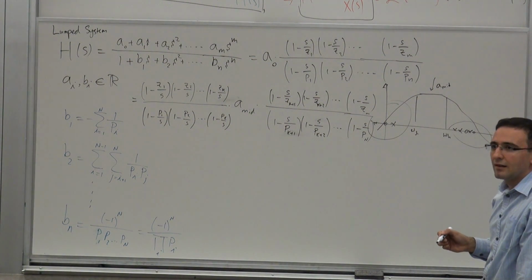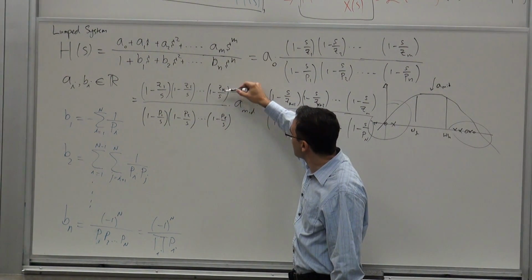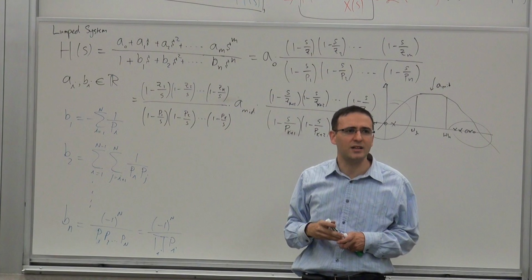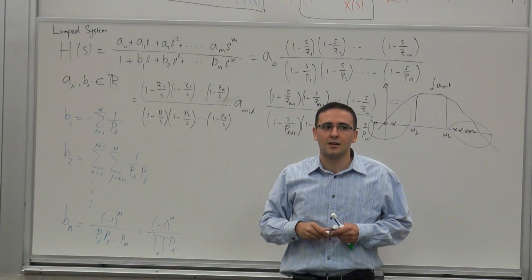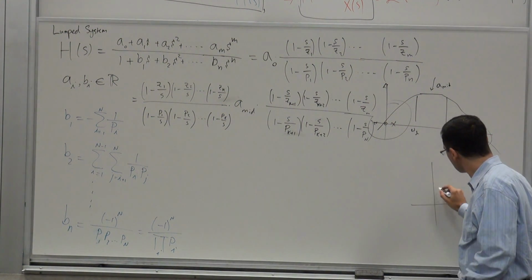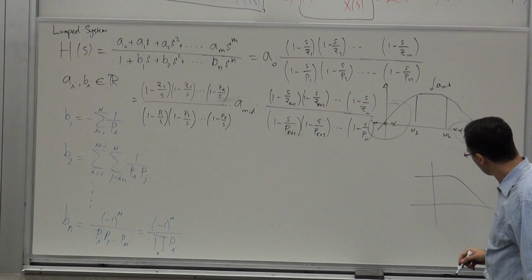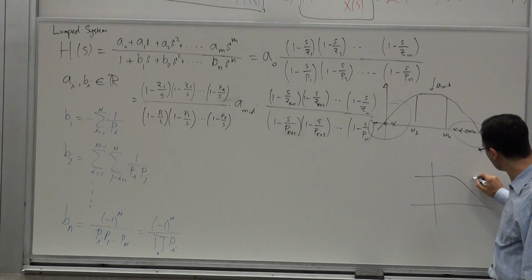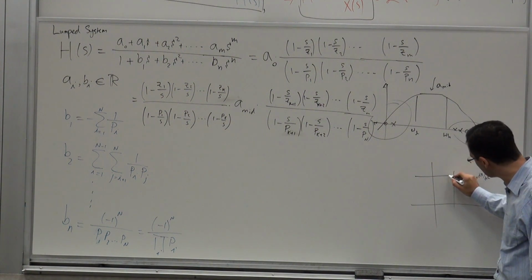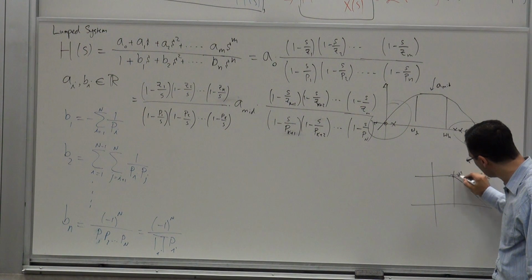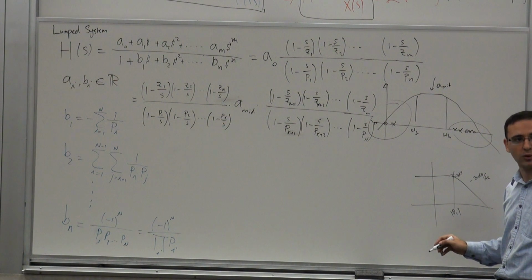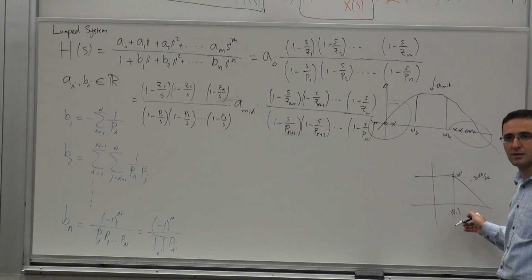So, by the way, I show them in such a way that they go to k, so I have the same number of low frequency poles and zeros. Why is that? Why did I do that? Because remember, and we'll see this, what do the poles do? A regular pole drops the amplitude by minus 20 dB per decade. So at the pole frequency you drop it by 3 dB, if you have a single pole on a Bode plot. This is the response of a single pole system, the first order system.